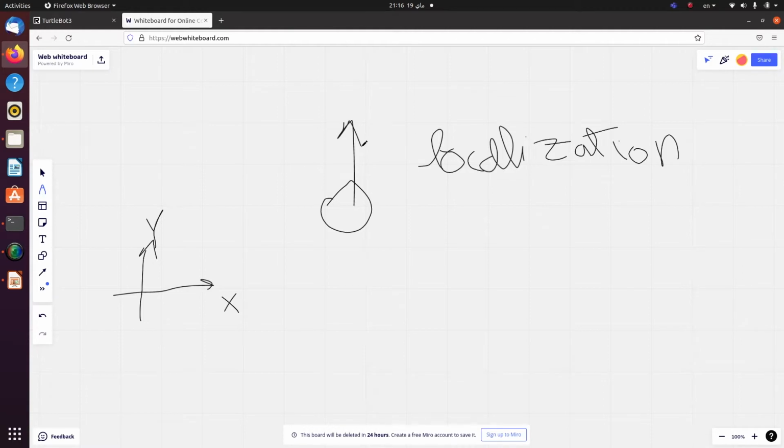The roll and pitch angles are always assumed to be 0 because we have some restriction forces, which are the ground reaction forces, because we have 2 actuation wheels and 2 caster wheels. And a caster wheel is a support wheel. So we always have the main wheels, the right and left wheels, which are responsible for actuation and motion, and 2 caster wheels, which look like your stroller wheels or supermarket cart wheels, which do not help actuate your vehicle.